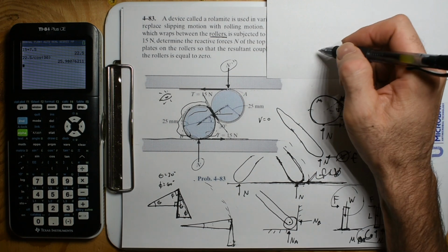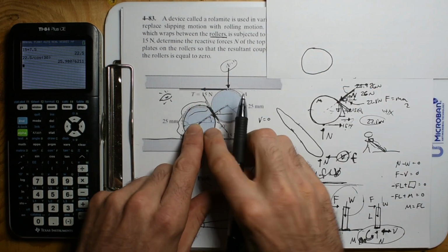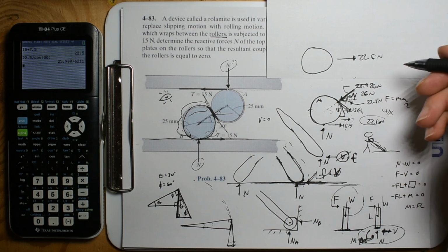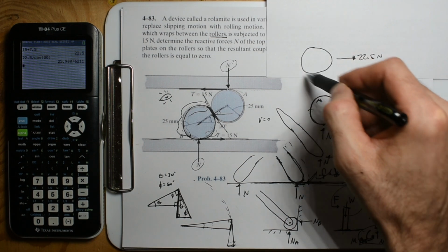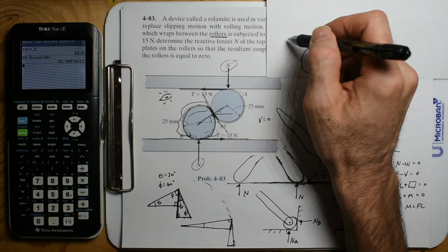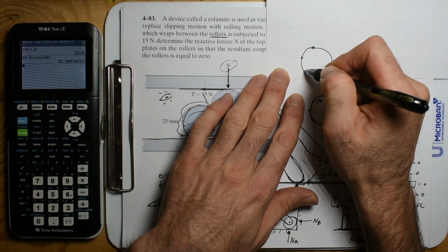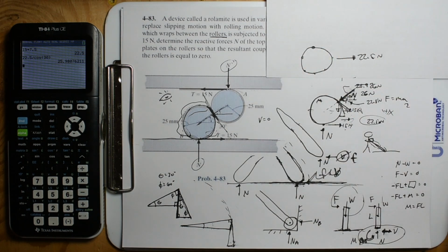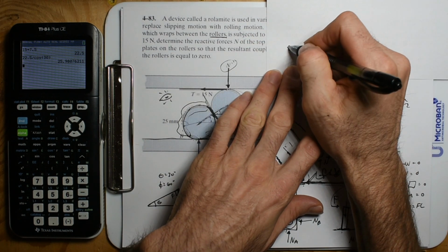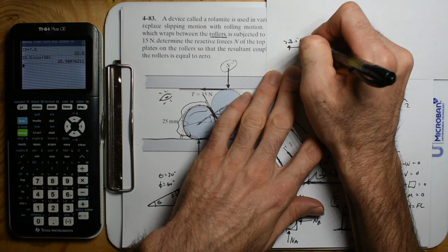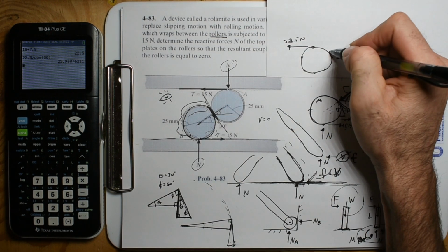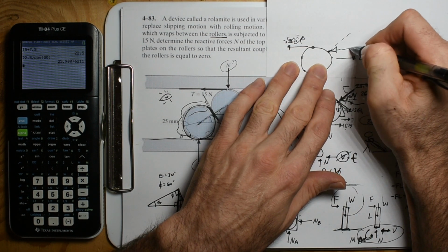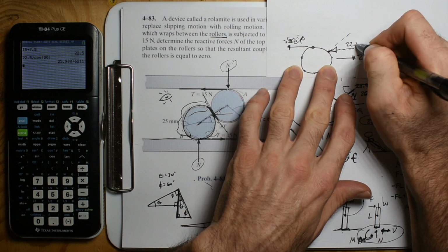That's basically like taking this mass, putting 22.5 newtons on it in that direction, and using that same principle. Like, hey, this thing's in outer space. We need a force going the other direction. It can be anywhere on here because we're not worried about this thing rotating yet. We just need something to balance it. So here, we could apply a 22.5 newton force in that direction, right at that contact point, and only this component of it has to be 22.5.